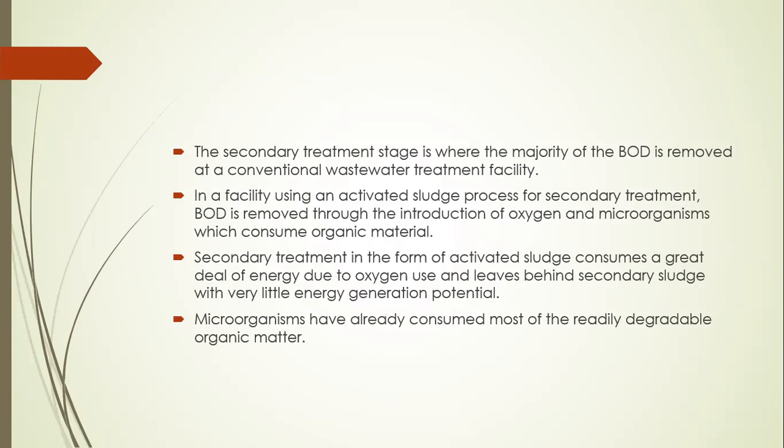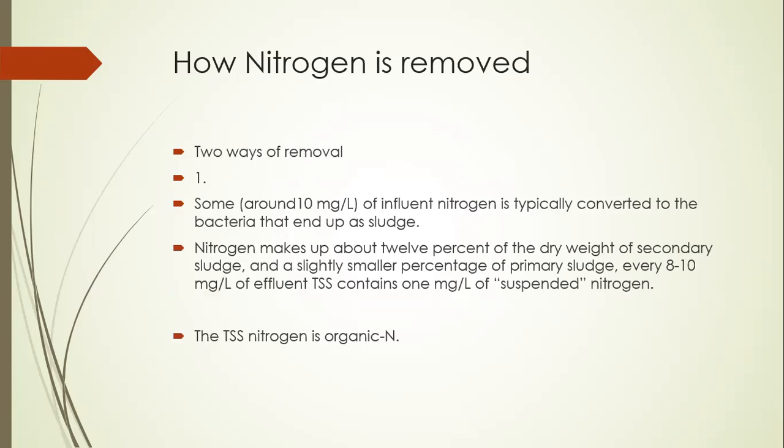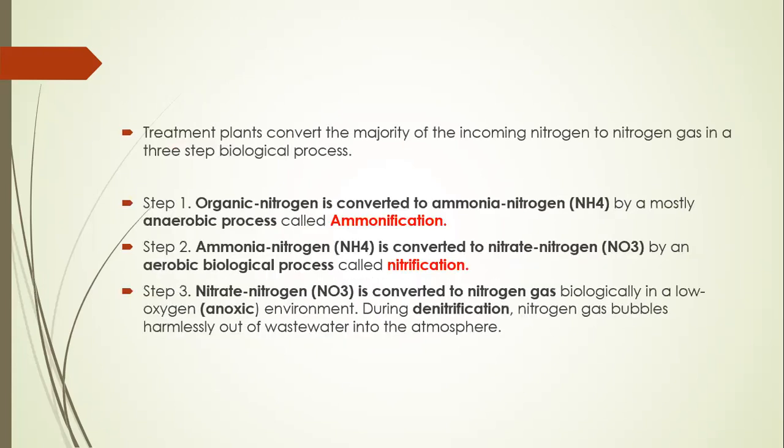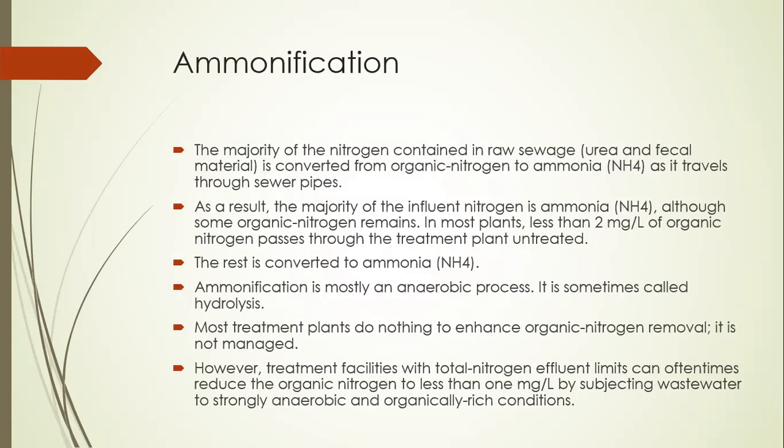You can have a look at the explanation I have already given. Nitrogen removal, as we indicated, is through tertiary treatment and a combination of anaerobic and anoxic treatment processes. So how is the nitrogen removed?